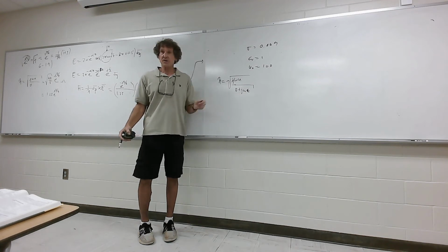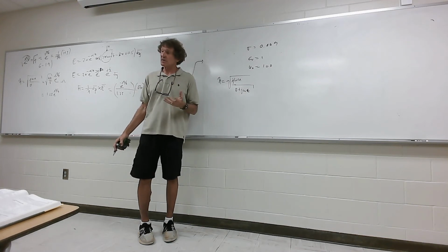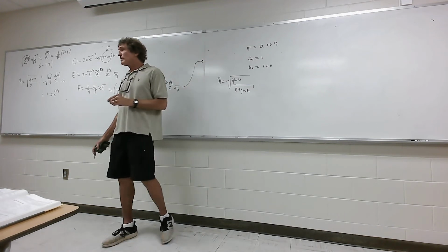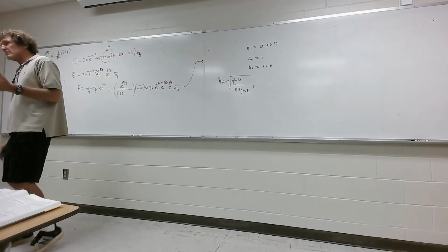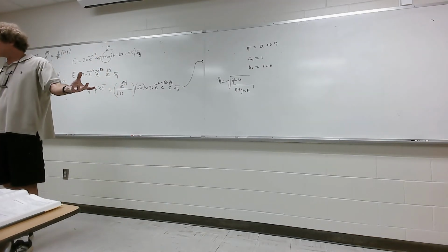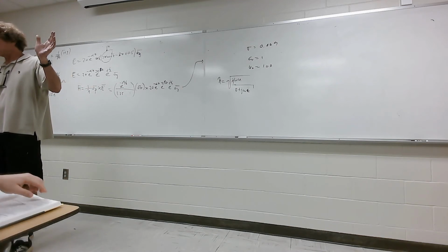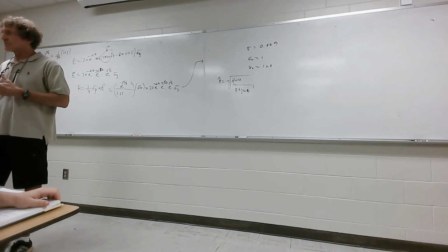If omega epsilon is much greater, then it's a dielectric, a lossy dielectric at best. What do you define as close, like same order of magnitude? Normally, if you have sigma 10 times greater than the magnitude of omega epsilon, it's probably a conductor. You can usually ignore j omega, unless you're talking about super precision stuff, but normally you don't do that.